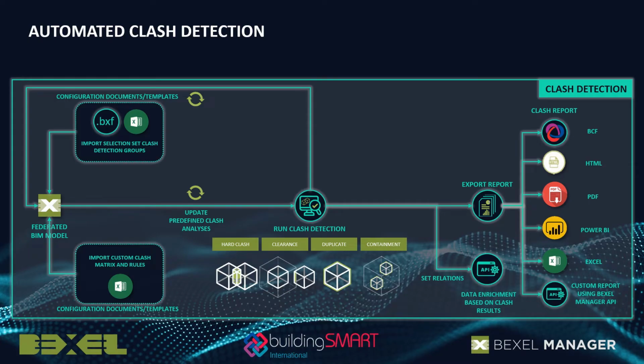After we have completed data management of our BIM project, the next logical step is validation of geometrical attributes of your model, or clash detection. This process again is a time-consuming process which includes a lot of updates, a lot of configuration of the clash jobs, a lot of work on organizing the groups of models that should be checked against each other and so on. And if we look at the process more in detail, again it's actually set on certain principles, on a certain set of rules that could be and should be followed on every project.